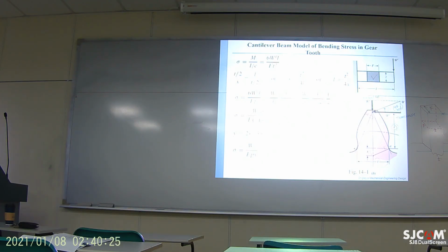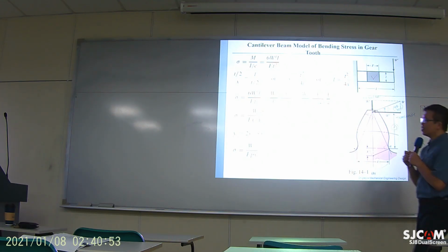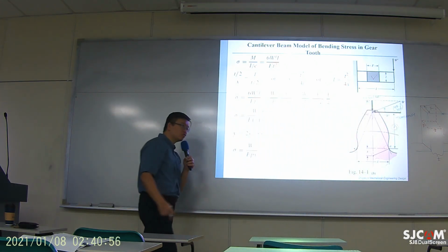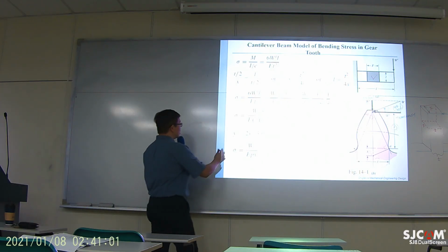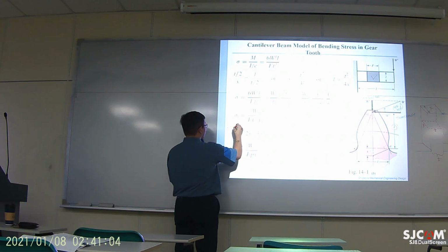So you need to make measurements of L and make measurements of T. So when you have a gear, you really need to use some kind of tool to make measurements, so you can study the stress. There's nothing wrong with it, but there's one way to normalize whatever is being studied right there, and it's called the Lewis factor.